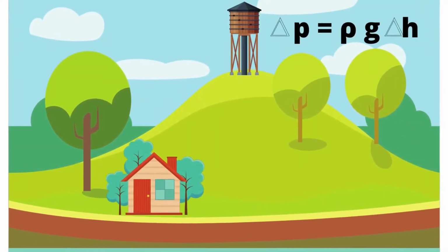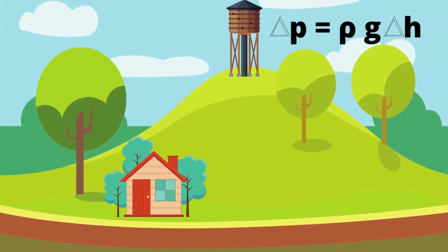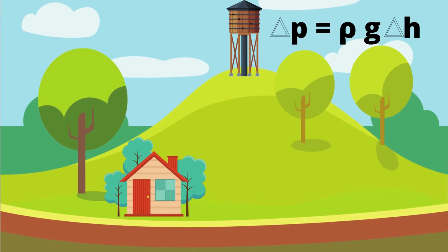The principal equation is that the difference in pressure equals the density of the fluid times gravitational acceleration times the total height. As for the application in a water tower, we can assume that the density is constant as we use water, and the atmosphere is also constant. Thus, by increasing or decreasing the height of the tower and the elevation of land, we can alter the amount of force produced to deliver the fluid towards surrounding buildings or facilities as needed.